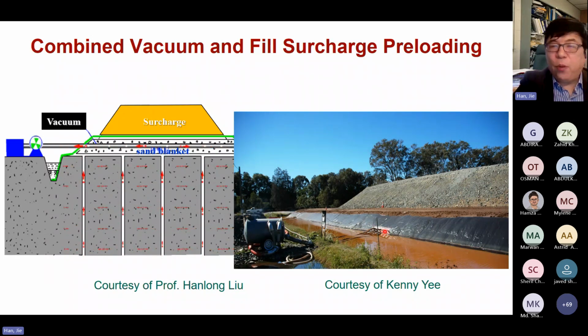Now there's a couple little details here. As you see, this is the trench with the water. The reason I have the trench is basically to try to stop the leakage at the edge of the geomembrane, to prevent the leakage.